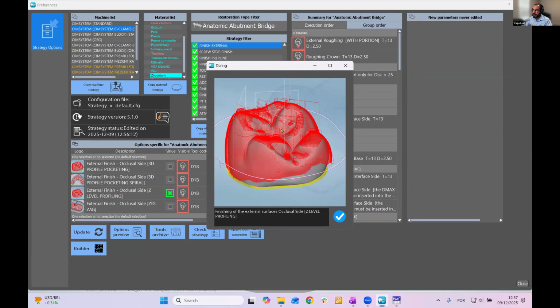That is the oldest type of tool path that we have, which works like a printer. You're familiar with the printing way, like the layers. It will be something similar, but from the top to the bottom, removing material from the top to the bottom. And we usually go back to mill some areas that are more flat, more horizontal, because since we are working in Z steps, considering the height, sometimes when we have a flat area, it might leave some material behind, so it will go back and refinish those areas.